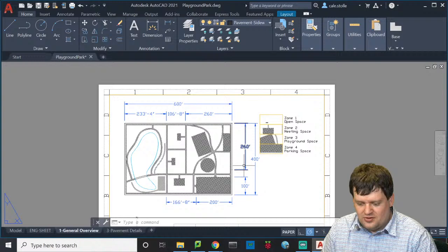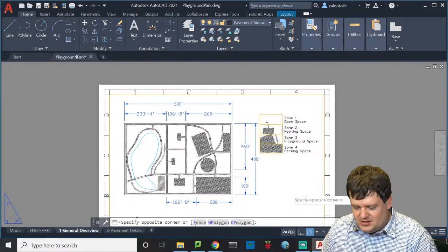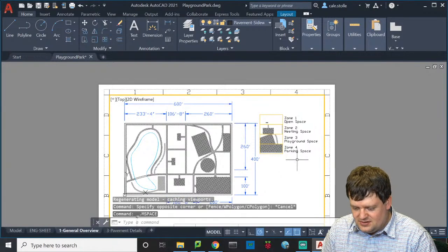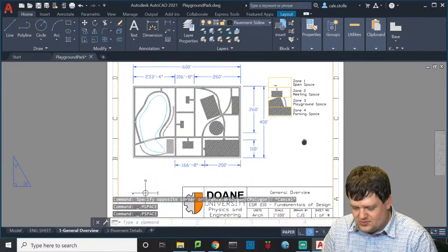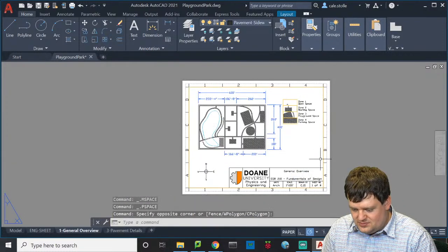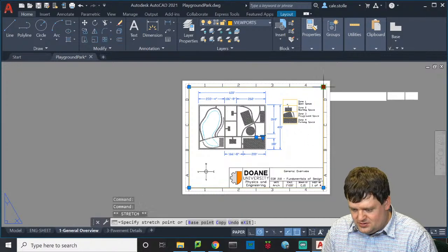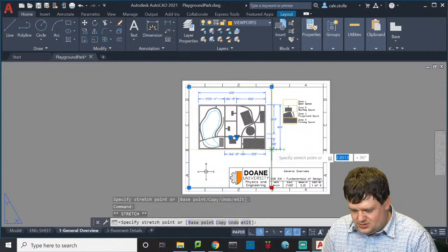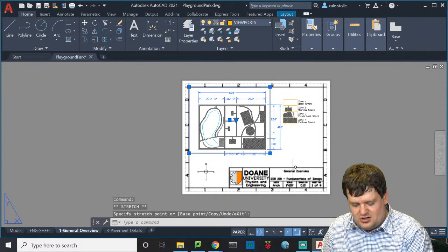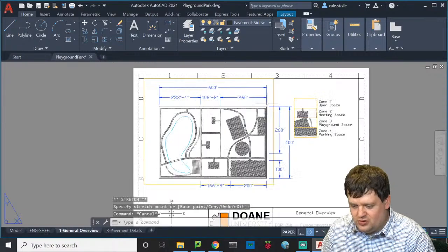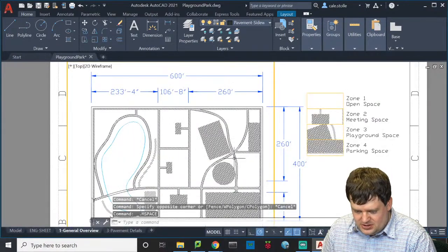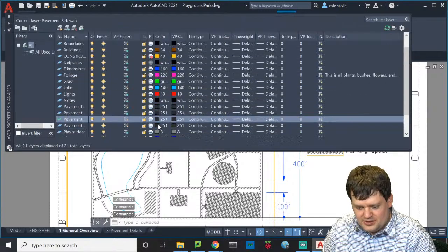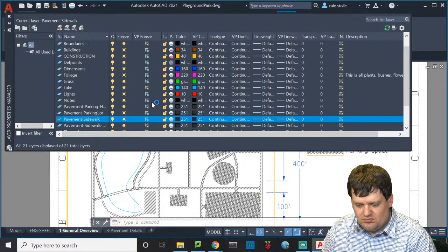Oh, gross. Oh, yeah, it's because I shut off the zones. So I'm actually going to click on this. Oops. Scroll so that before I do anything, I'm going to shrinkitize this, so it's just larger than what I'm trying to show. I'll zoom in here, double click, go into layer properties, and shut off those two hatches that I just created. I don't want them showing up.